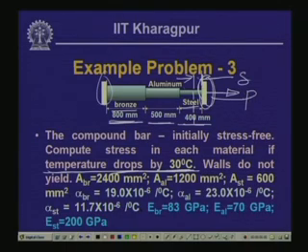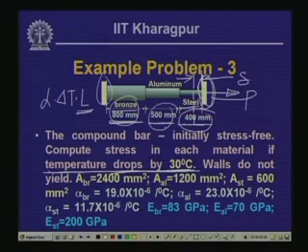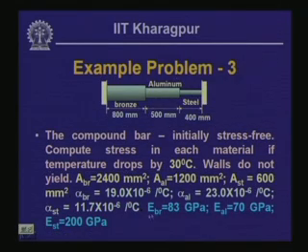Now, the deformation because of the change in temperature is alpha times delta T times L, and over the whole length L, we have three parts: 800, 500 and 400. So, we can compute the values individually and calculate delta. After computing delta, you can find the value of P and equate these two. The total strain is equal to the strain due to P. So, calculate this. Next time we are going to discuss this particular problem.